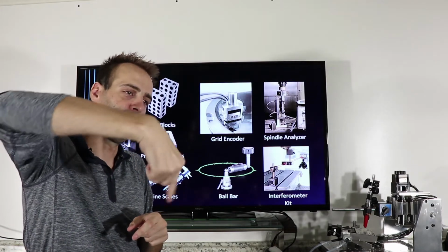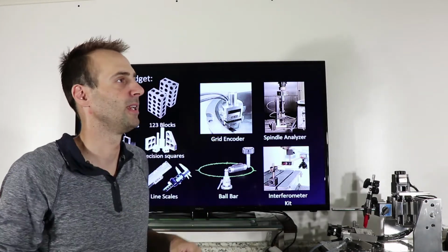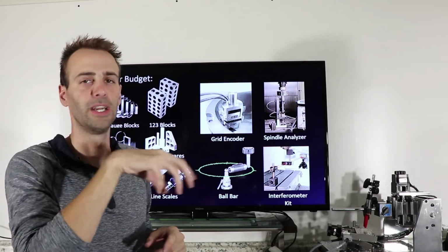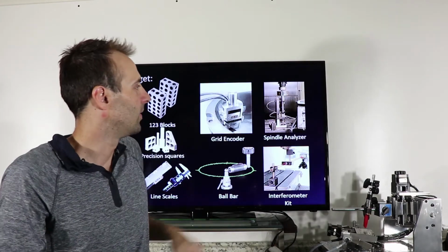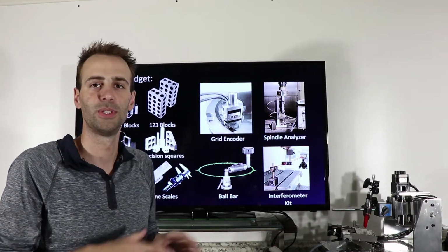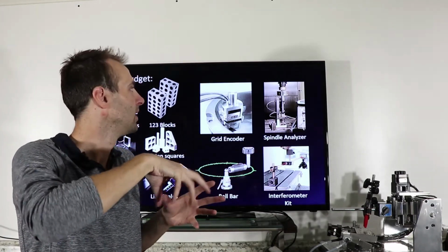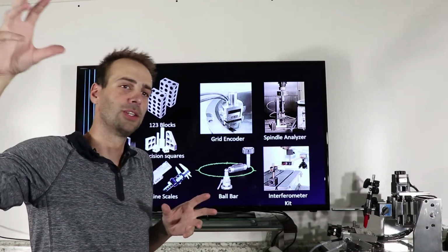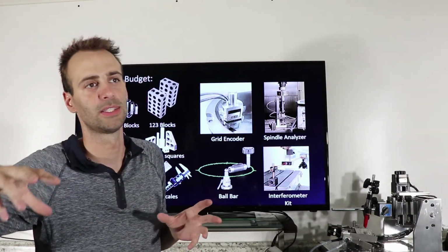If it has an angular wobble, you get it from the difference between the bottom and the top. If it's moving anywhere in the XY plane, you see it both on the top and bottom. So it's a little bit tricky to set up, but what's really cool about that setup is you could drive the spindle in there, let it do its thing, come back, put that thing in a tool changer, do some machining, heat up the machine, run it through its paces.